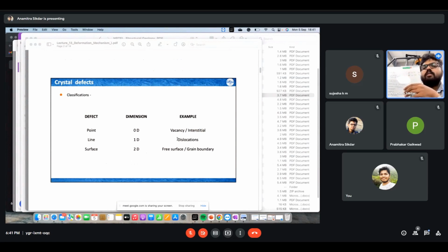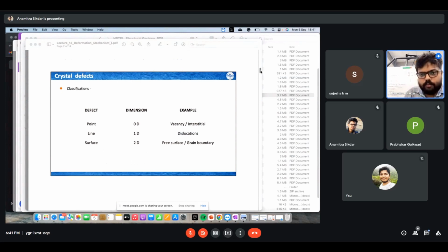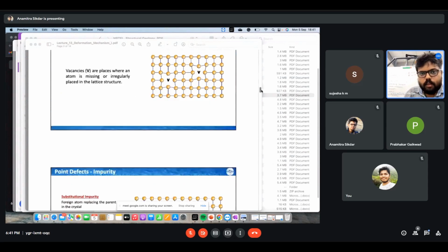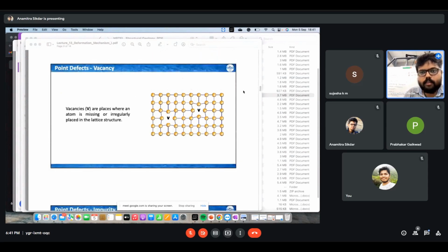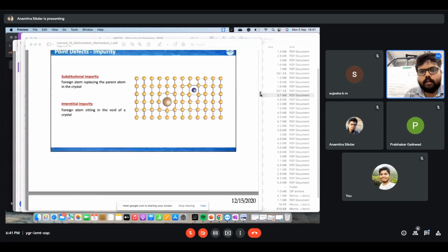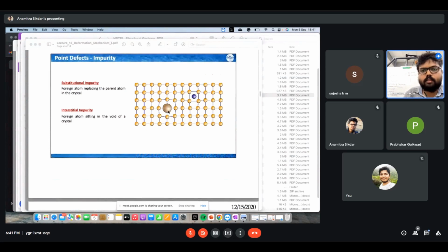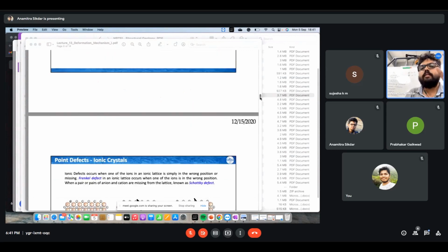Those are termed dislocations. We have a picture of point defects here. We have vacancies in the crystal array, and maybe some interstitials, ions which are not regular ions, something different, something bigger. This creates a kind of strain inside the crystal, right?